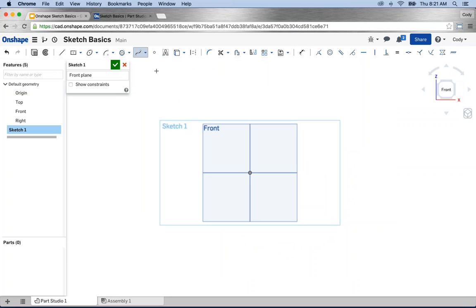I'll left-click Spline in the toolbar. And initially, when you first start, we'll left-click and then move the cursor. Initially, it looks like a simple line. It isn't until you add the second spline point that you realize that it behaves a bit differently. So if I left-click now, I can bend and manipulate. So it's essentially a free-forming entity.